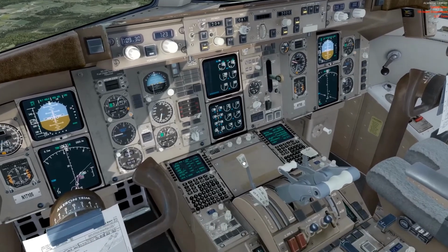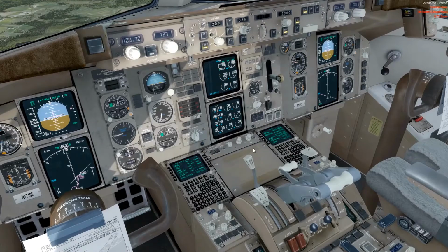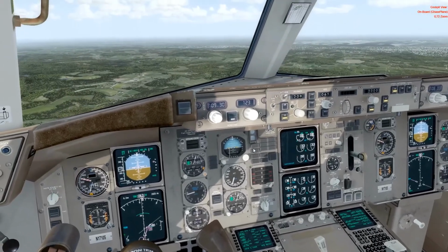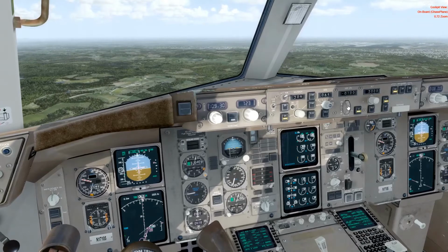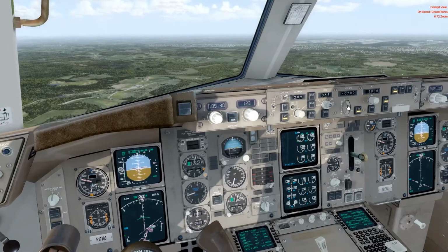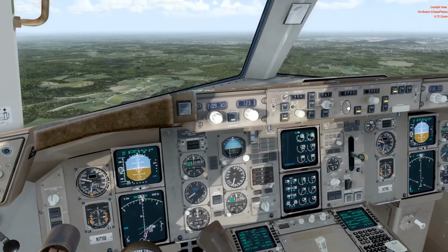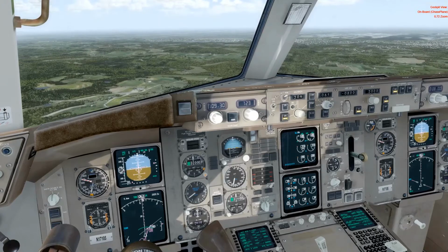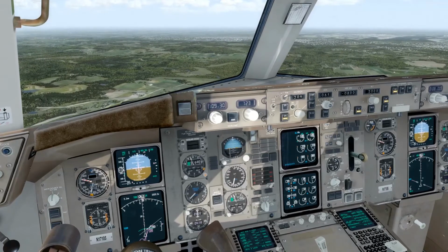One thing we want to do is to arm the speed brake. This will cause the speed brake spoilers to automatically deploy once we land. So the speed brakes will automatically deploy once the wheels touch the ground. This will help slow the aircraft down.